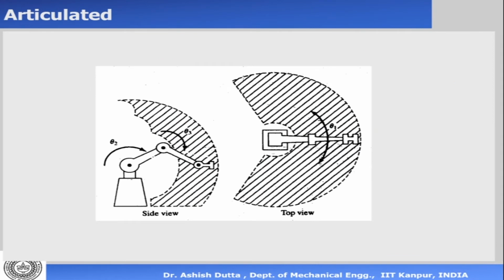Let's look at an articulated robot. Okay, an articulated robot has 3 revolute axes or 4 revolute axes. So let's call it 4 DOF, 4R axis. Okay, now let us see how we are going to draw this. Now for simplicity, let me assume that we are drawing the case for a 2 degree of freedom system, just for simplicity. So 2 DOF, 2R manipulator. So this is a 2R planar manipulator.